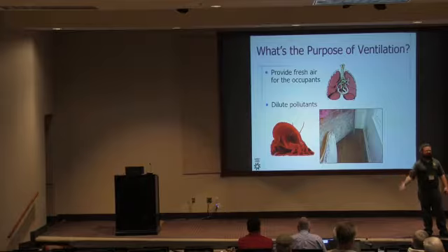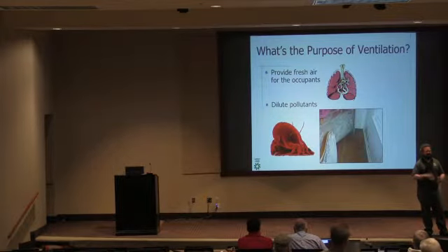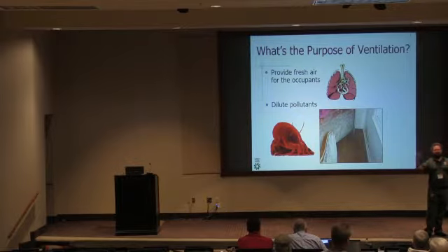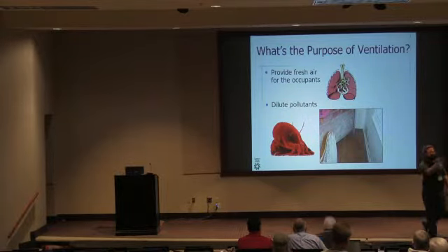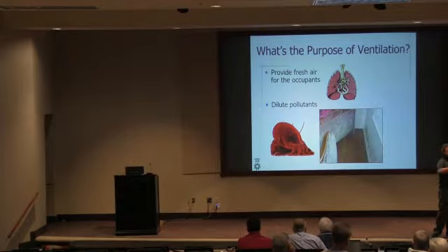And the programmable thermostat, aside from being more complicated, in the modern world, she and I don't work 8 to 5:30 Monday through Friday. I'm here, it's a Saturday. She's working too. She's off on Wednesdays. I'm working from home on Tuesday, blah, blah, blah. Trying to set a schedule that says every single day the system should turn on now and turn off at this time becomes an operational nightmare. And then you're using override all the time and it's complicated. So programmable thermostats can save energy because they can put the house into setback when it should not be running.